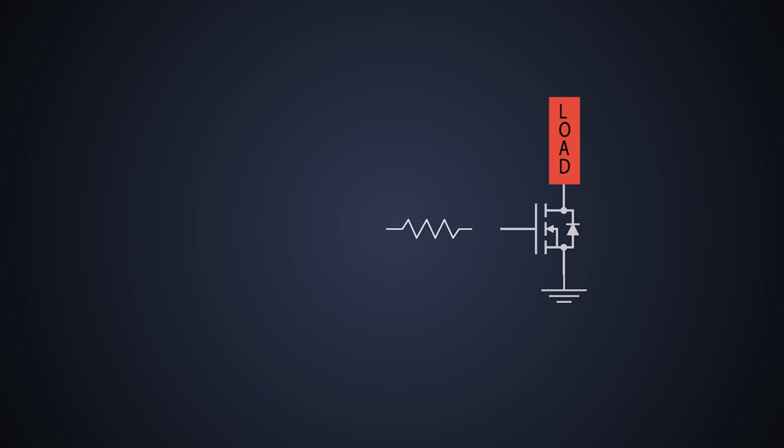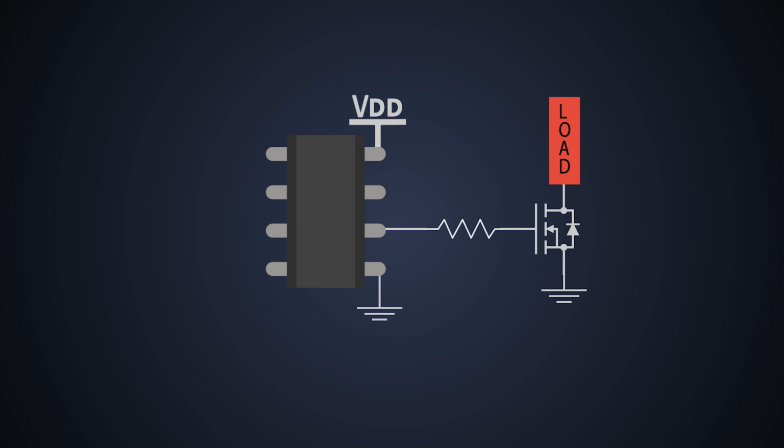To minimize this problem, we can drive a MOSFET through a gate driver IC or proper gate driver circuitry. A gate driver circuit has a very low output impedance. Because of that, the gate voltage doesn't exceed the maximum gate voltage during normal operation, and it doesn't cause any voltage ringing in the circuit.